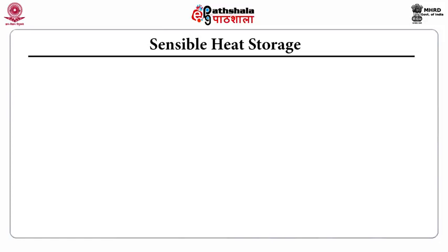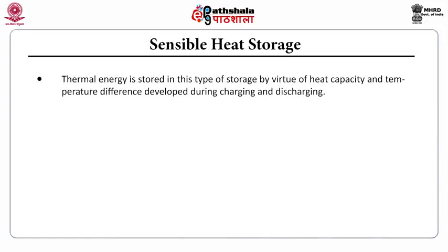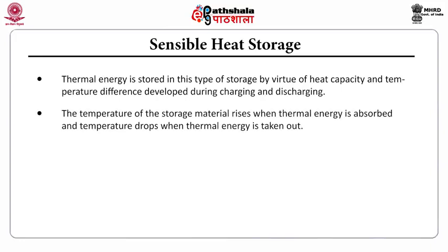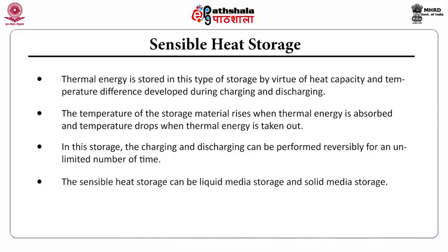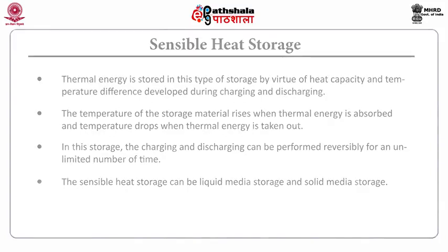Sensible heat storage. The thermal energy is stored in this type of storage by virtue of heat capacity and temperature difference developed during charging and discharging. The temperature of the storage material rises when thermal energy is absorbed and drops when thermal energy is taken out. In this storage, the charging and discharging can be performed reversibly an unlimited number of times. The sensible heat storage can be of liquid media storage or solid media storage.